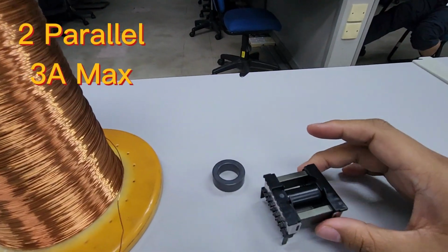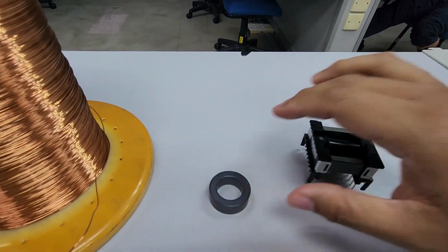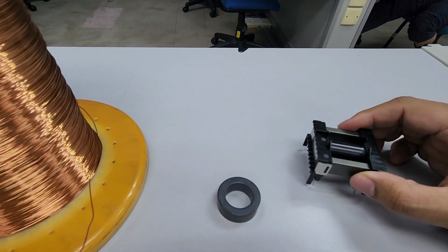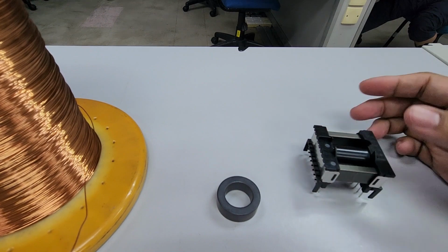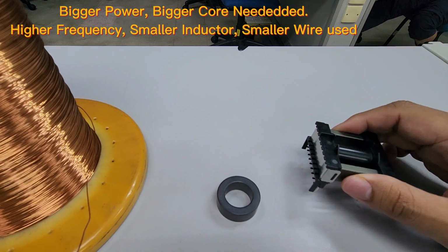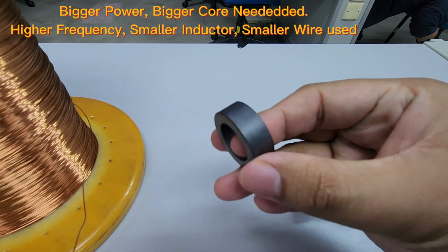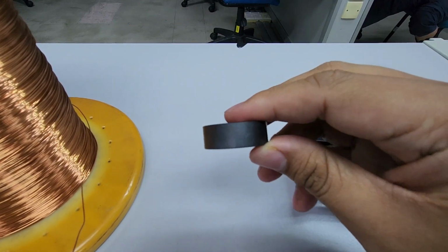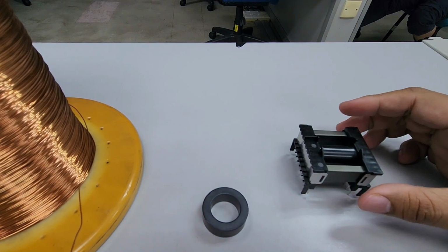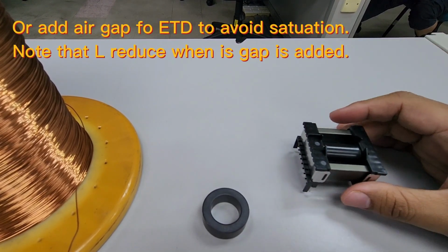You can use either a toroid or ETD. The toroid is the smaller one, and ETD is the larger one. It depends on the power. If your power is very high, you need to use the bigger one to store the magnetic energy. But if your power is low, around 10 watts, 20 watts, this one should be okay. If it saturates, maybe you have to make it larger, and buy the larger one.